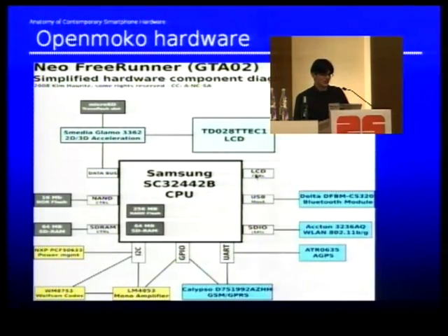Yeah, we have an LCD controller that is obviously connected to the LCD, not disconnected, and there is, oh no, sorry, no, it's actually true. The LCD controller is not used, the built-in LCD controller of the SoC is not used in this hardware revision, but there is a graphics accelerator, in quotes, connected to a display module. This is the LCD display. And that one again has an SDIO interface which connects to the SD slot because, well, the SDIO controller here is used for the Wi-Fi interface. So you see the kind of problems.